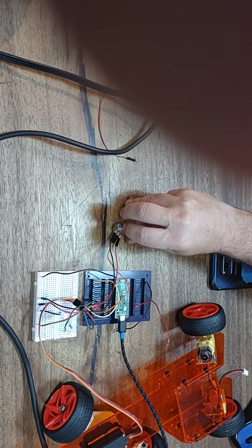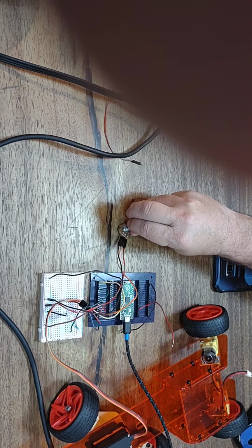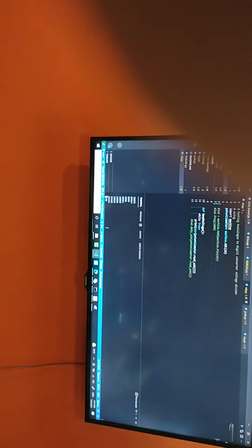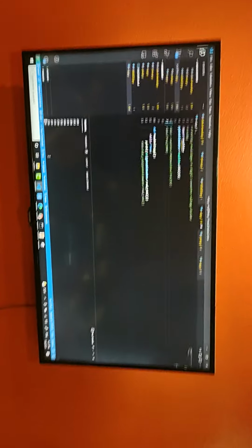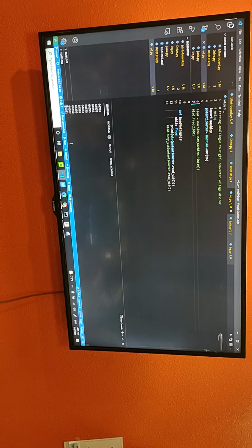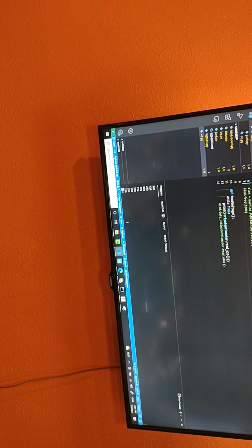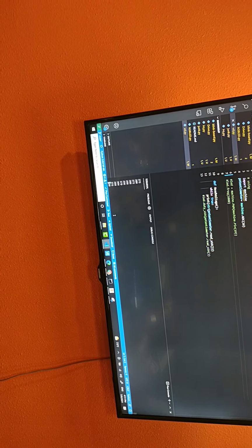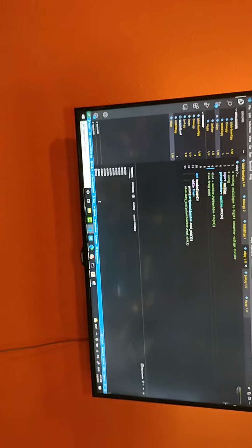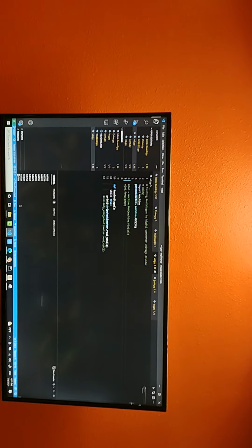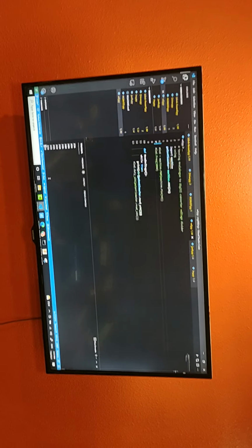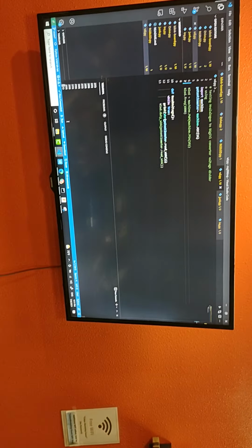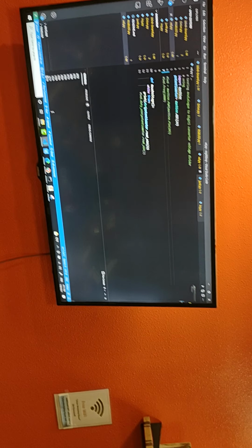What is the significance of the pound sign LED dot duty? Is that marked out? Yeah, I'm going to show that next. Am I supposed to see a sleep anywhere? It's going down, almost to 0. It's between 200 and 65,000. It's not expected to get down to 0 because of issues with potentiometers. There's always going to be some resistance. Where is the sleep you mentioned? We don't have a sleep in this case. I'm just letting it run as fast as it can.